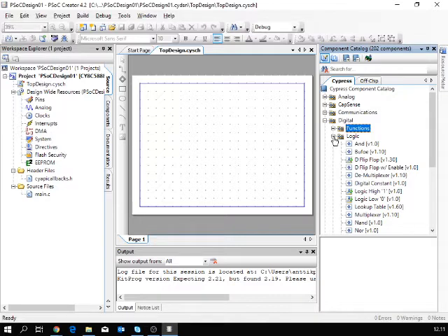If you have two hardware blocks, then you can take the outputs and combine them with AND or OR, combinatorial logic, in addition to these block functions, which is nice, since the more you have on the blocks, the less code it requires. Those digital and analog blocks are running. You just have to start them, configure and stop. It runs independently. Okay.